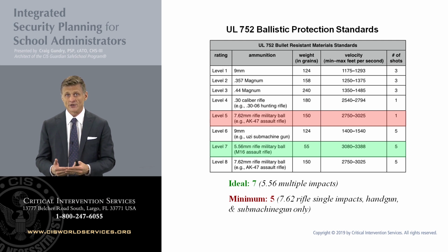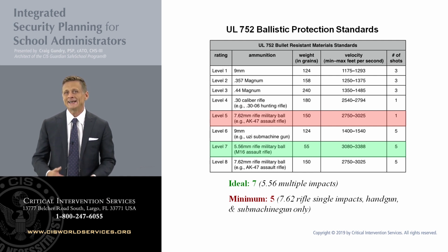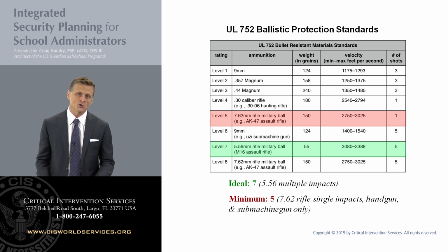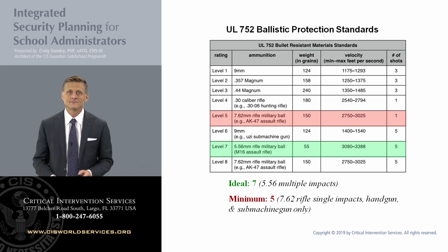Well, the problem in this situation is that because of the dense group of people all packed into this very tiny room, a gunman did not need to get into that room. All he needed to do was fire directly through the door and could guarantee hitting targets on the other side. So in that situation, I did recommend installing a ballistic resistant door for that safe room. But trying to upgrade every door throughout a facility, every door vision panel, every window, it just doesn't make sense. Instead, I prioritize intrusion resistance first.